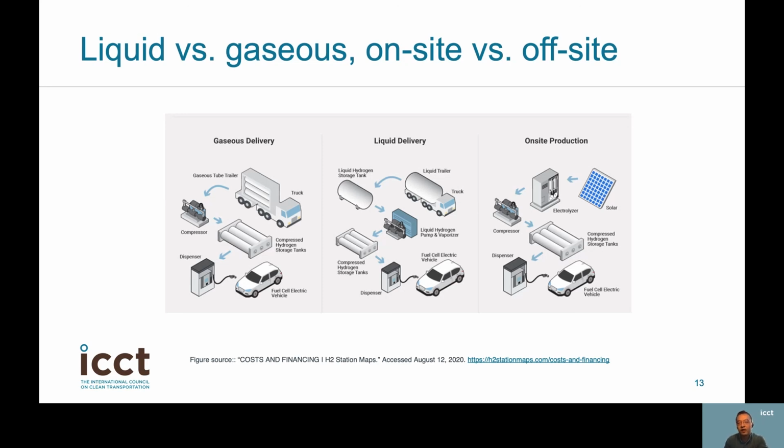Having hydrogen fuel produced off-site and delivered to a bus depot means less equipment to maintain, lower energy costs, and is a similar procedure to diesel delivery, which operators may be familiar with. A large centrally located hydrogen production facility off-site can produce hydrogen at a lower cost because it is producing more, but it costs more to deliver the hydrogen because the point of use is farther away as the hydrogen boils away. Ultimately, the storage option decision will still have to be informed by hydrogen consumption modeling, consultation with bus manufacturers, and space and location constraints.